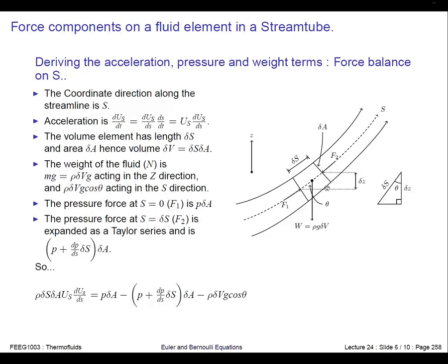Okay, and I've got the weight of the fluid. So I said the component of my weight acting in the s direction is the cos theta. And as we can see from my sketch, this means my force is acting in this direction. And this is the opposite sign to the positive s direction. So I'm putting a negative sign here. So here's my force balance that must hold. So what we need to do now is clean it up a little bit and make it a little bit more useful.